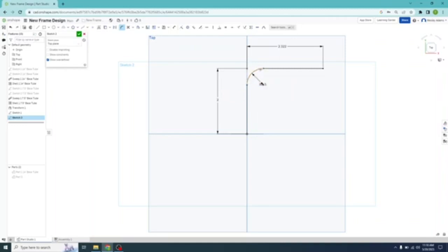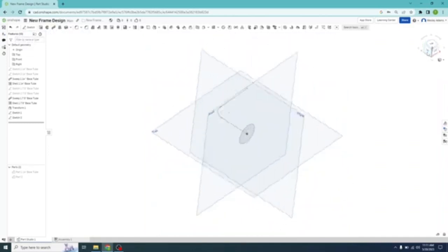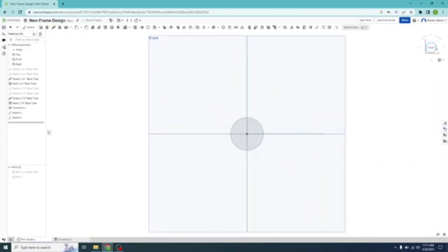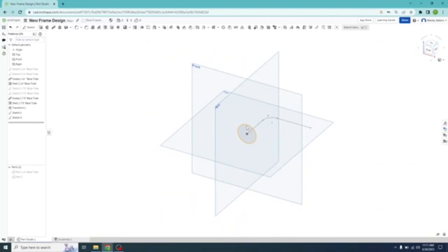And so you can see how it created the bend. So that is the radius here of the bend. I'm just going to drag that down so it's easier to kind of see. Go back and we're going to select the dimension tool again. So left click on dimension tool, come down, select the first line, come across, select the second line, and we want that set at 90 degrees. I'm going to go to isometric view so that we can kind of see the angle, the circle.